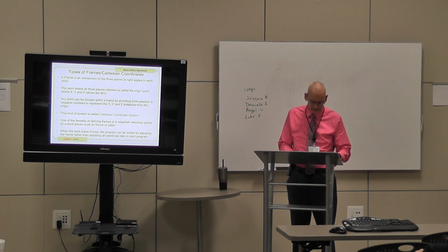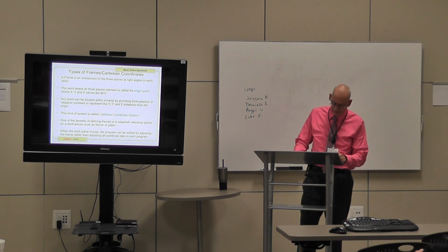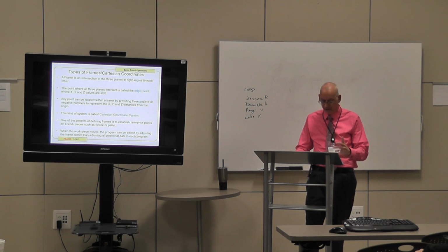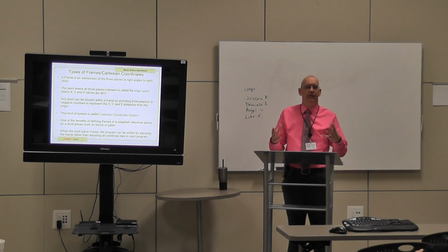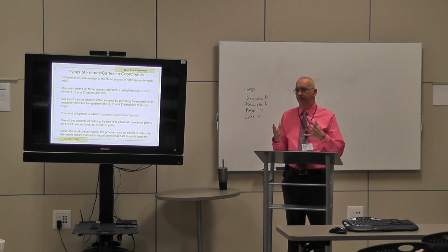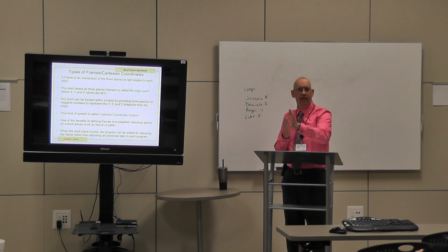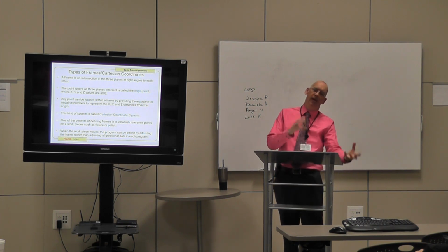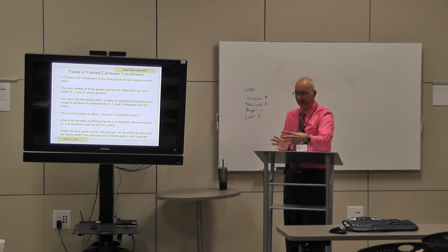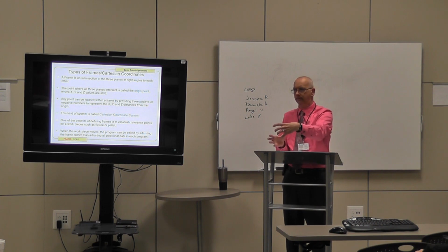One of the benefits of defining frames is to establish reference points on the workpieces such as a fixture or pallet. Let me explain that a little differently in manufacturing terms. We have the assembly line, and on that assembly line, we have a robot that has to do something. We have a frame that is designated and defined for that robot to operate, and it has a certain tool on it.